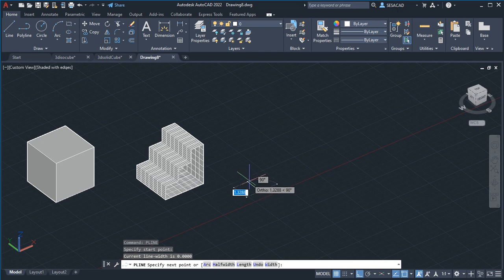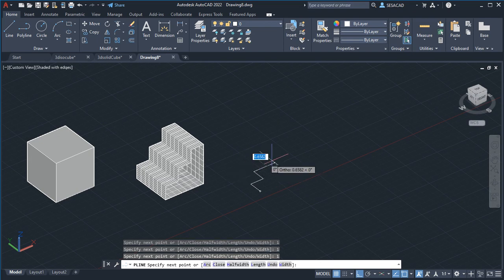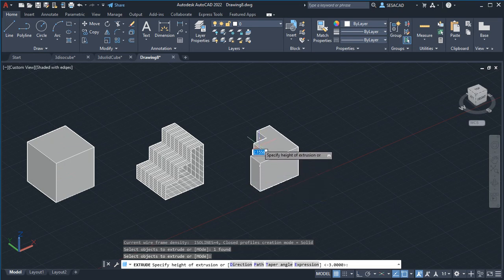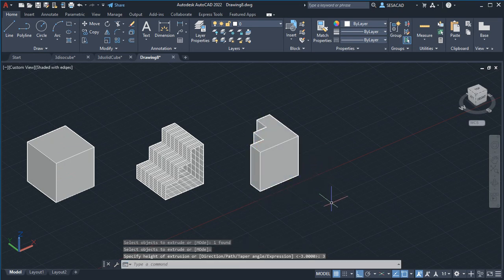You can only do upward, I mean, y-axis 1, enter, x-axis 1, enter, y-axis 1, enter, x-axis 1, enter, y-axis 1, enter, 1, enter, go down on the negative y, and then put in 3, enter, and then back to the start, enter. You can have that, and then you can extrude, and then when you extrude, it will extrude as a solid object.